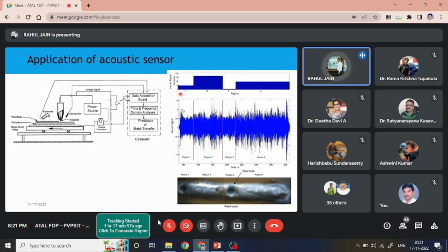For example, in region 1, you see there is a defect. In region 2, if you see the bead size, it is fine, it is good, even though there is a smaller defect over here, closer to region 3, but it is fine. At region 3, because this value is very low, there is a bigger defect. Here, everything is smooth, right? That is why it is indeed.